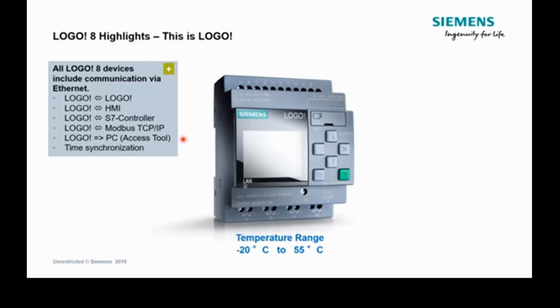If you have your Logo connected to an Ethernet network and somewhere on that network is a PC, as long as Excel's installed onto that PC, we can install the add-in to Excel, the PC Access tool, and that then will pull data from the Logo and populate that into an Excel spreadsheet as live values, or you can slightly adjust that syntax and also log that data into CSV files directly on the hard drive of the PC. So obviously they're then available to you so that you can copy and paste them off onto a USB stick or whatever it is that you need to do without affecting the operation of the Logo, because there's no interaction there at that point with the Logo. We've just read the data and stored it in the files on the PC.